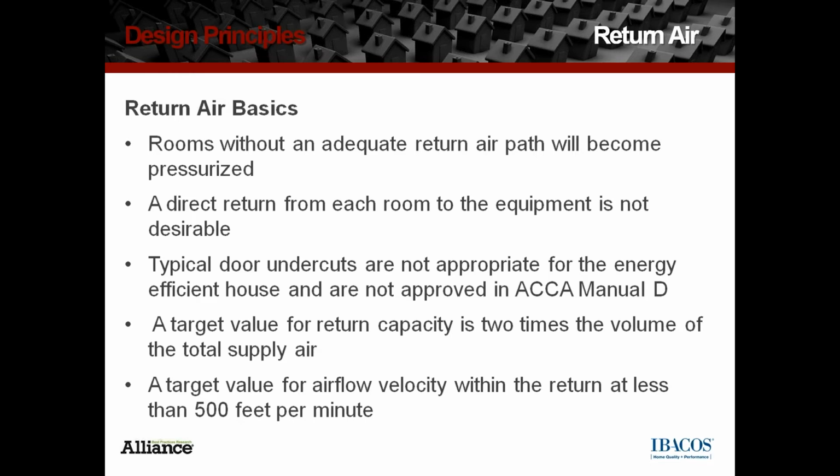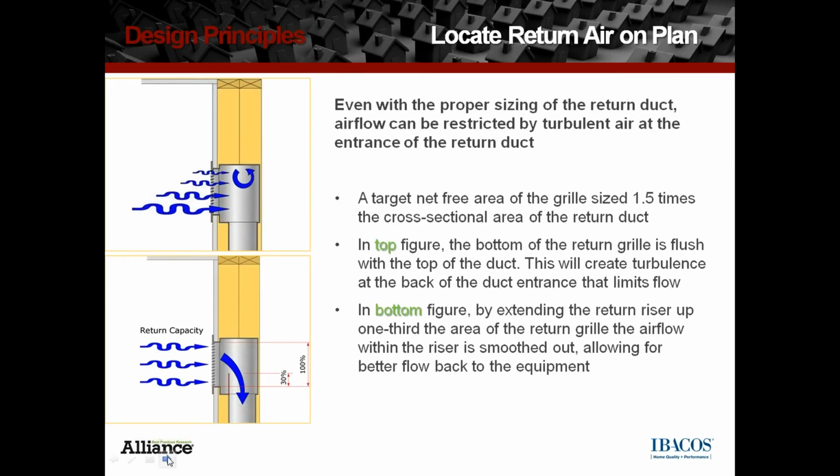We say here in the second bullet point that a direct return from each room is not desirable. It's not the best strategy because you have to account for all that return air ductwork in your duct length as you're calculating your duct system. So what we're going to talk about on the next slide is the use of a central return. No, I've got to talk about this first.